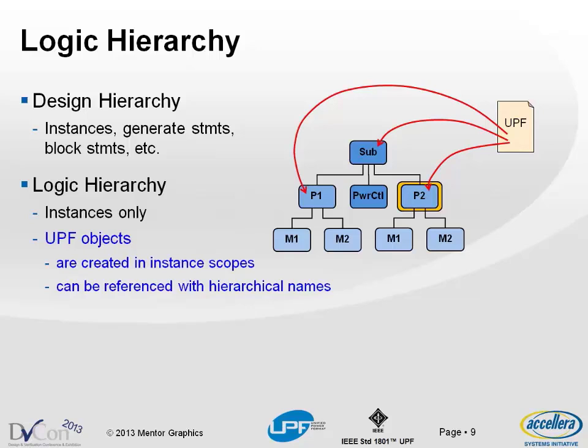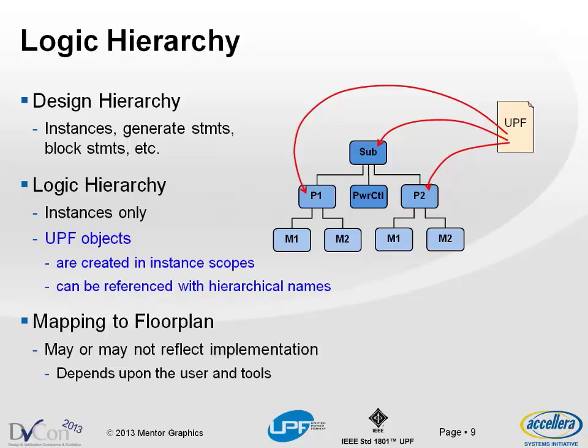That's the fundamental concept. A related question is, does this hierarchy that we're working on represent the ultimate implementation in terms of the floor plan? And the answer is, it depends. Some people really like to think that. They like to keep the logical hierarchy in their HDL aligned with the way they're going to implement it in the floor plan.